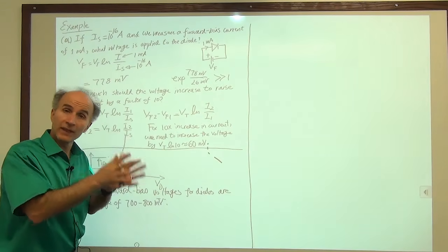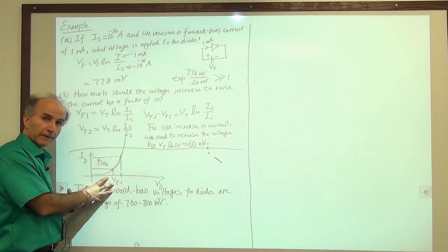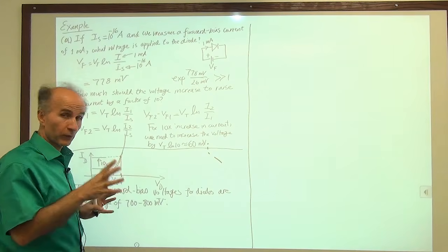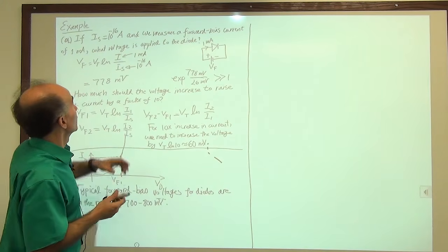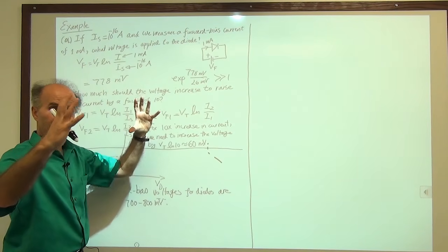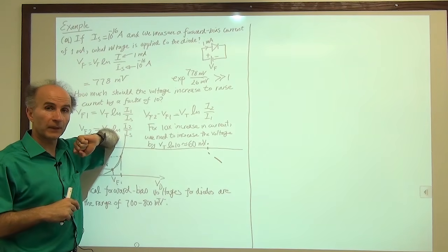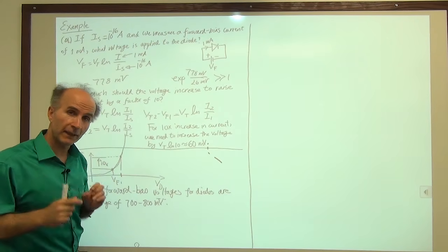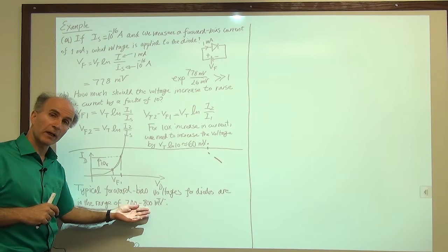And such diodes do exist, but they are not what we are considering in our application. And in fact, if you have a diode that is designed for 1 ampere, you will not have an IS this small, because that diode will be large in area, in junction area, so its IS will be large.